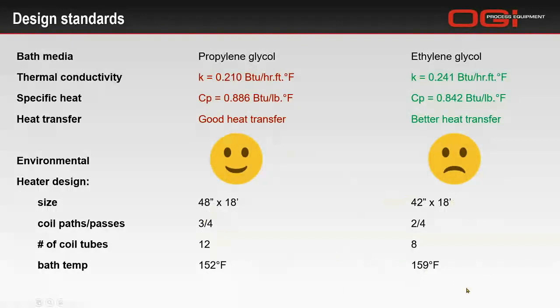So again, I'm not advocating one versus the other, just wanted to show you the difference and the impact that your glycol could have on the performance of your heater. And all of this will relate to not only the thermal efficiencies, but also the combustion efficiency within the fire tube.